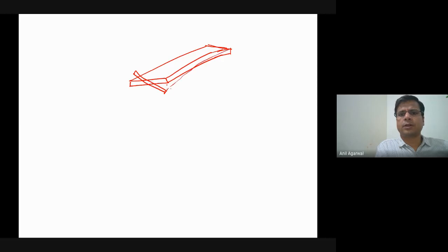Then what you are getting is this kind of movement. This is a twisting movement. You measure this theta, and how much theta is changing with variation in z will control how much twisting is happening. So d theta by dz will tell you the rate of twisting.